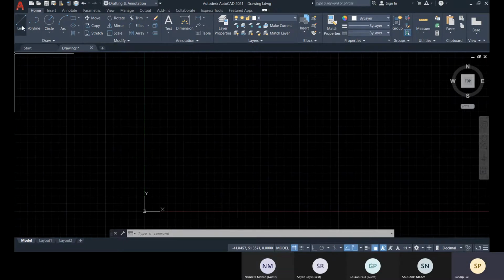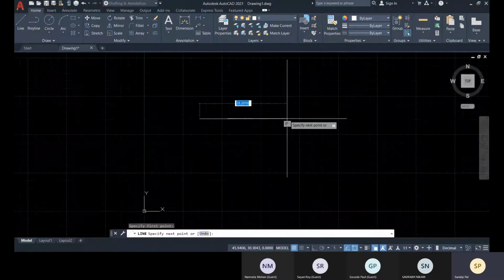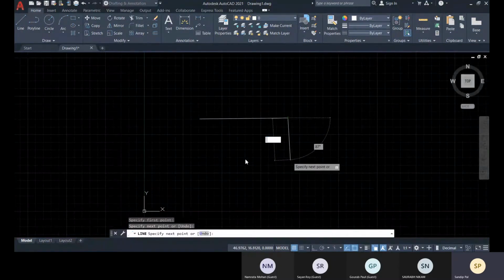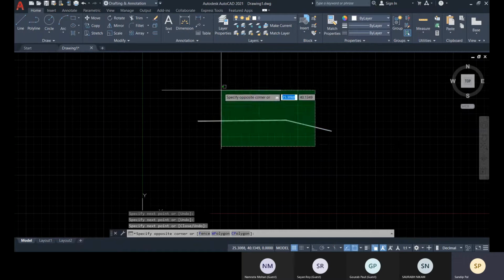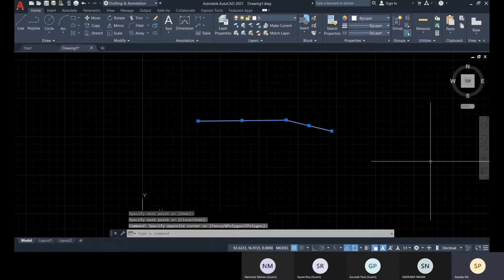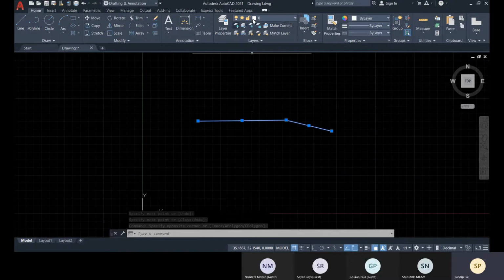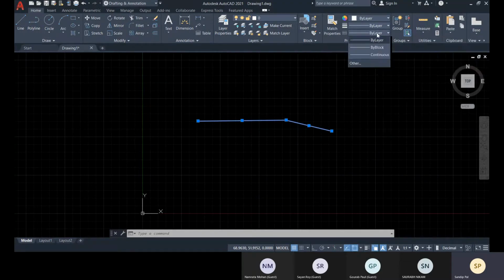All right then. Suppose we are creating any object, either a normal line or rectangle or any curve like an arc or circle. Each and every object has a line type. That can be assigned through layer, or I can override it from here as well. Always it is assigned with the layer first. With this default layer, the line type is continuous right now. So let me override.